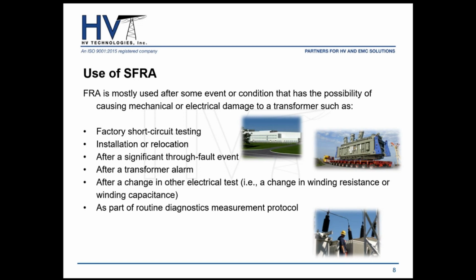It could also be used if a transformer is taken offline to be relocated, or if a new transformer has gone through some sort of transport to get to a site. It's always a good idea to run a sweep frequency response analysis on a transformer after it's been transported, just to make sure that during that process, it has not suffered any mechanical damages.